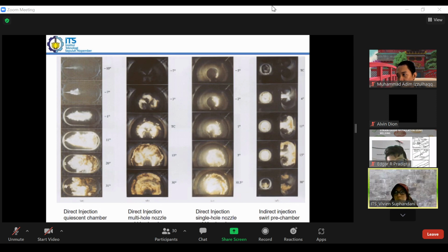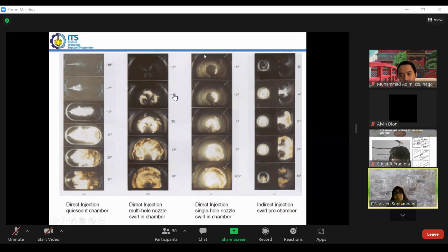To condition the fuel means to increase the turbulence intensity, to increase the swirl, and also to increase the temperature with the glow plug itself. So it becomes hotter. At higher temperature, it will be vaporized easily, so that it will be burned easily. So that will be the explanation, Antim.